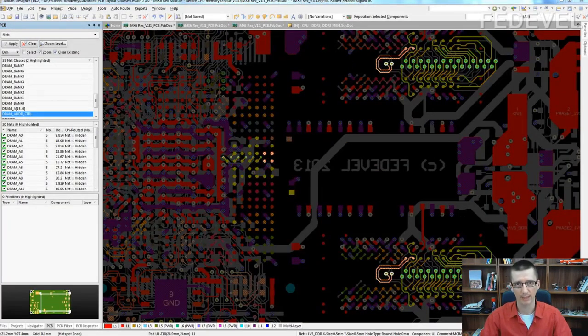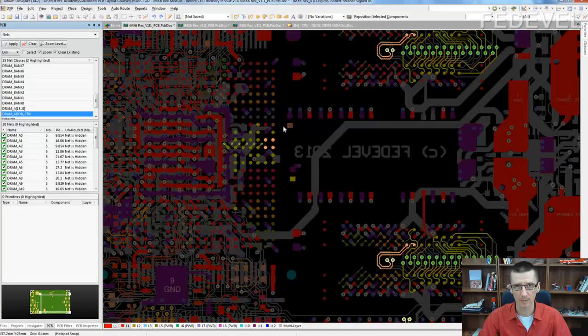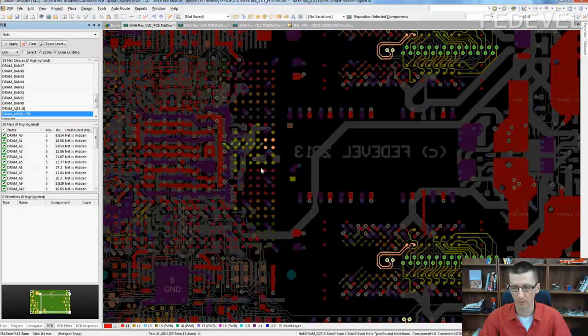Once you are done with the address, command, control, and clock groups, because you need to fan out also the clock groups between the first signals. They are really important. And they are located here. Then once you are done with this, continue with the data signals which are located close to this address, command, control group.